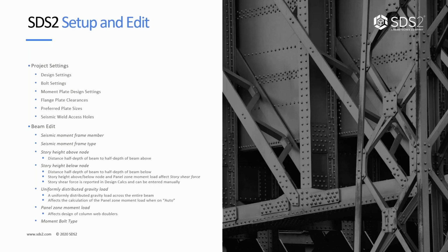Moment plate design settings, we've always had those for a long time in SDS2. Those are going to affect things like our doubler, stiffener design. Keep in mind though, with those doublers and stiffeners, especially on the IMF and SMF, there are some pretty specific detailing requirements for those to clear the K distance on the column and such, which limits the contact that we can have there. And we'll see that happening as we go through the demo here in a little bit.